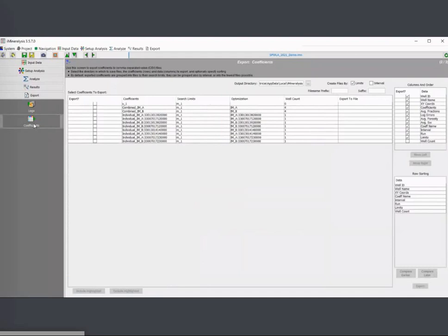You can also export the coefficients too, and this is a very unique feature of iMineralysis. You can export the combined minerals that we selected for each interval A and B. So basically, you are exporting only 2 different matrices, but you can also export in a CSV file, for example, the values for interval A of all your coefficients. You can select here to the right what information you want in the CSV file. It also allows you to export the average fractions, like the fraction of the minerals, like the volume of calcite and dolomite, etc., which is usually hard to export in a petrophysical software.